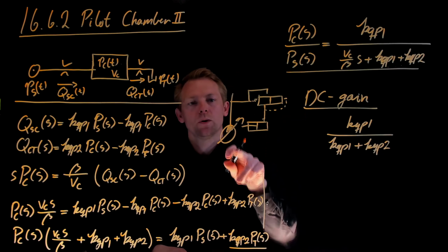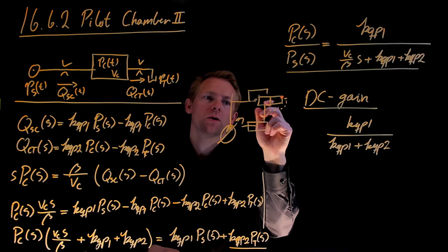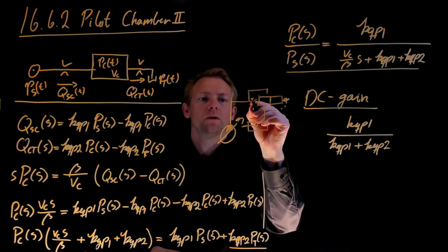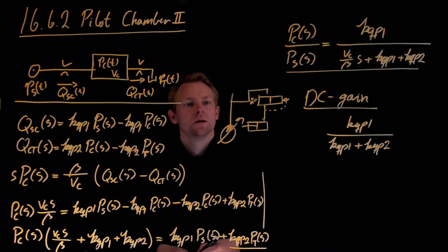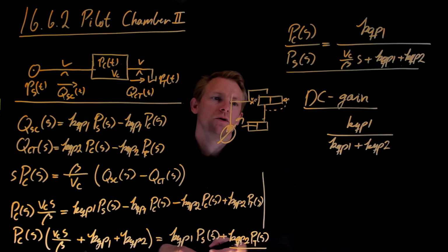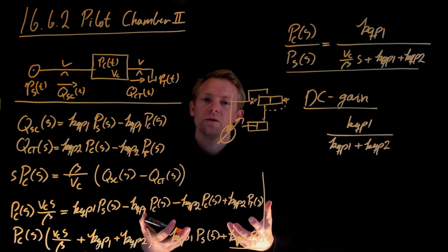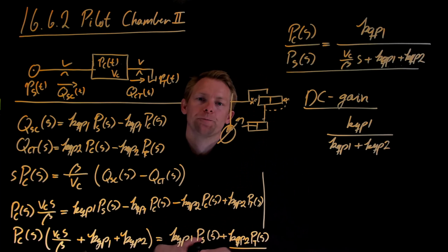And if we don't want the pressure pulsations that we have here to go directly into this valve, well, then we can put on a small orifice here. Could be that we have a bleed off orifice to another point. So in a system like this, or in another valve that is controlled by a pilot pressure, that's a place where we can see this.